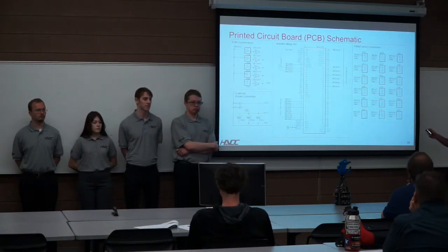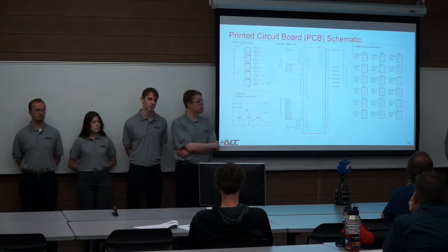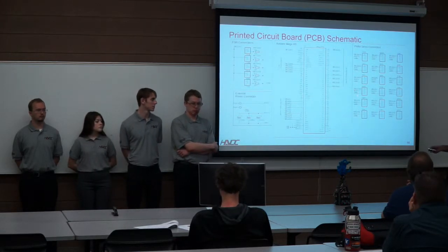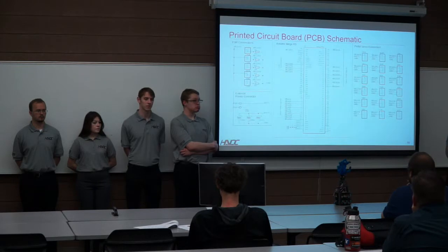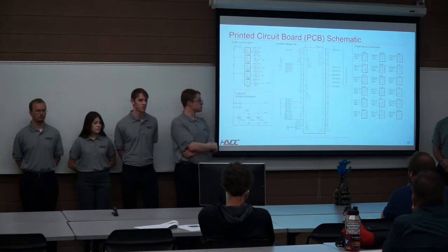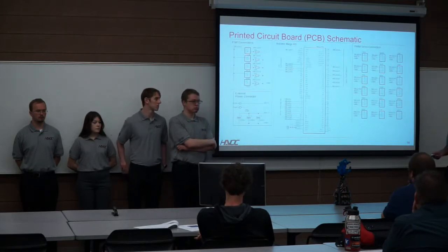So here in the notation, you can see the first pin is labeled Mega 13. This attaches to Mega 13 on the Arduino Mega R3. This is the same for the battery and ground across the schematic. We have 10 kilo ohm resistors attached to the force-sensitive resistor connections to provide a voltage divider so that we can read an accurate value across force-sensitive resistors that we may attach.